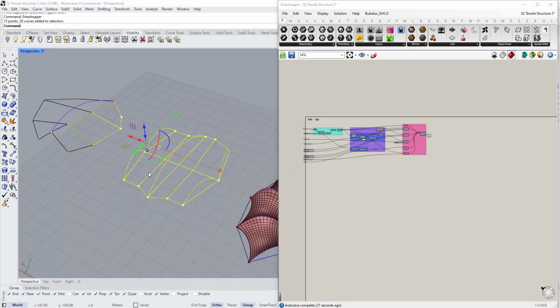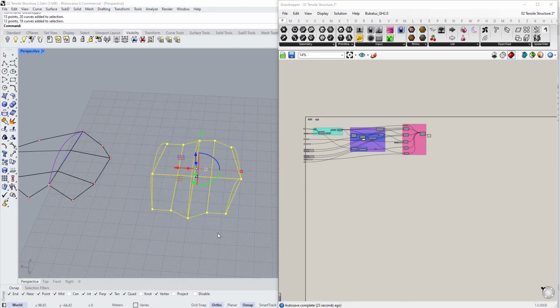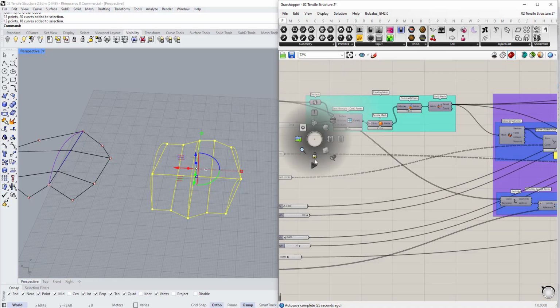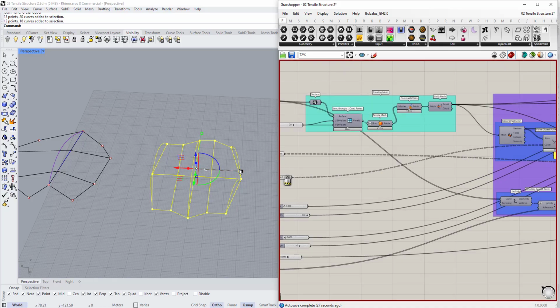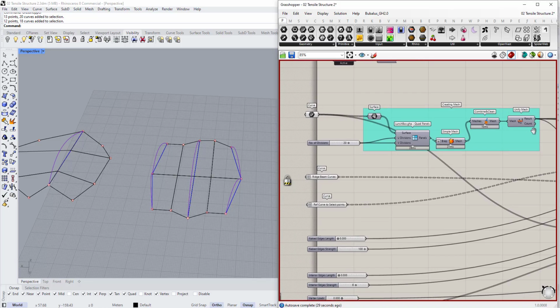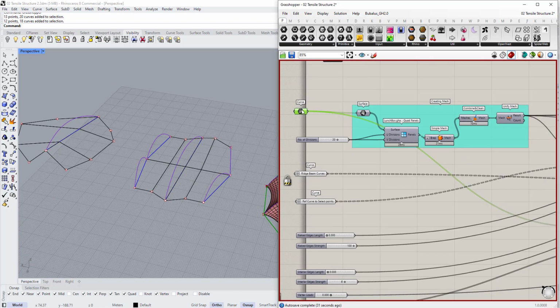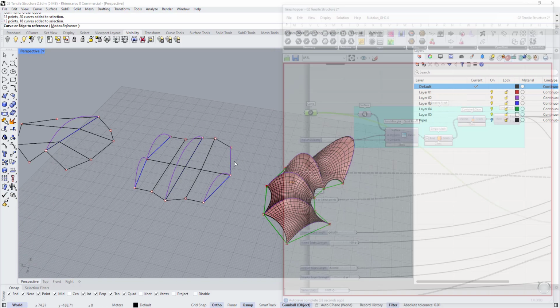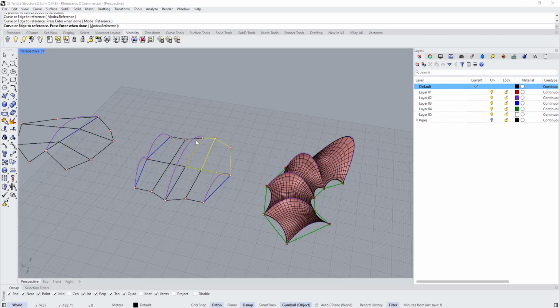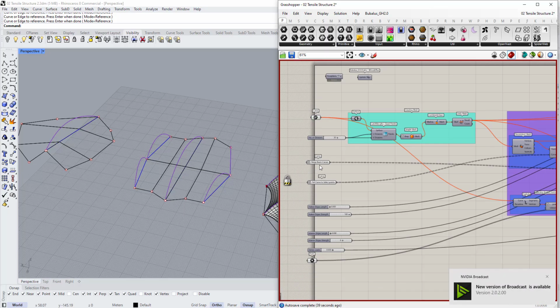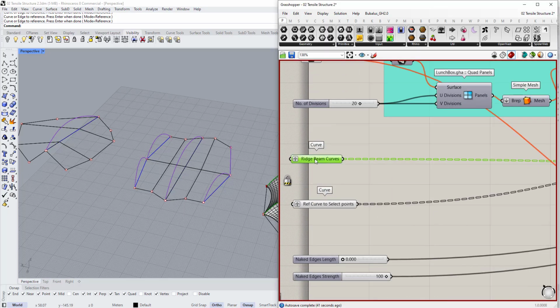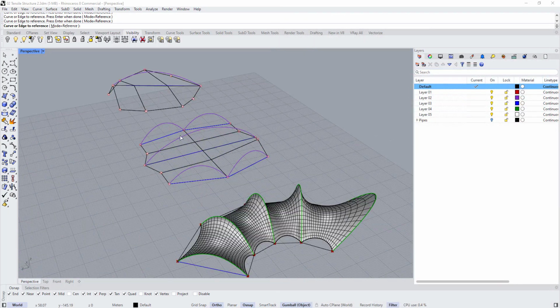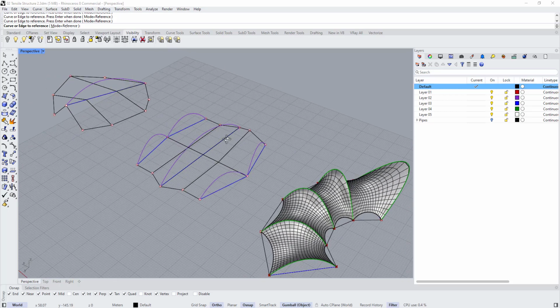Now I want to test these inputs, so I'm going here, click on the mouse middle button, and let's disable the solver, and let's start selecting the curves for the mesh. So set multi curves, select this one, this one, this one, this one, all this curve, right click, and for the ridge beam, set multiple, and make sure to remember the order in which you are going to select them.